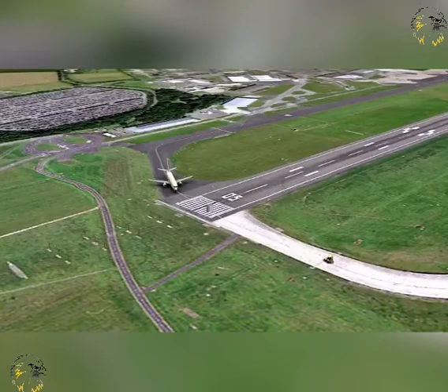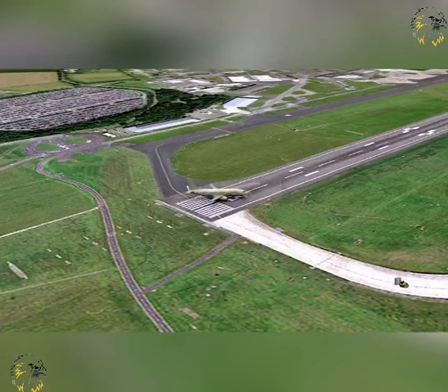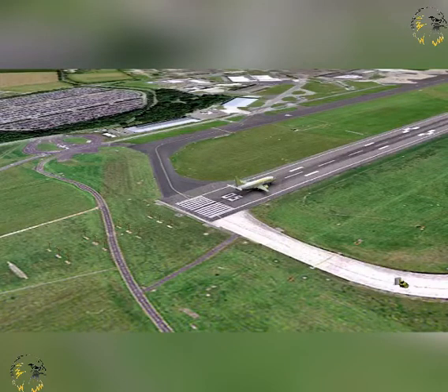No fixed object other than visual aids are permitted on a runway strip within 77.5 metres of the centre line for Code 4F, Cat 1, 2 or 3 runways, or 60 metres for Code 3 or 4 Precision, Cat 1, 2 or 3 runways, or 45 metres for Code 1 or 2, Cat 1 runways. No mobile objects are allowed within the runway strip during takeoffs or landings.